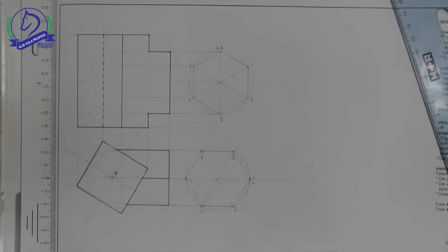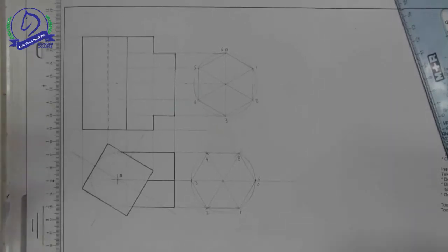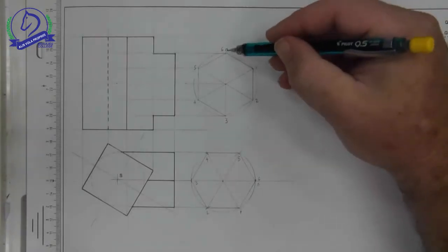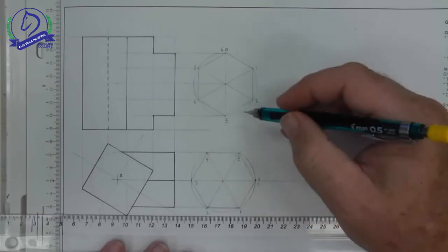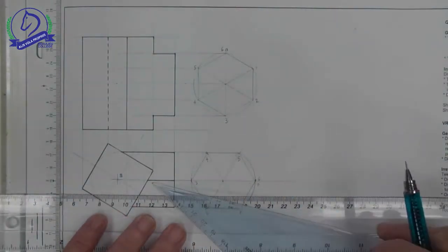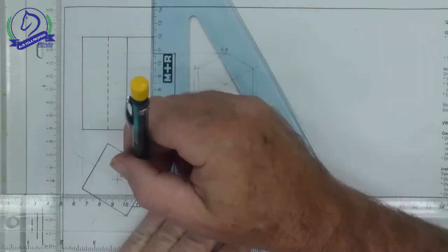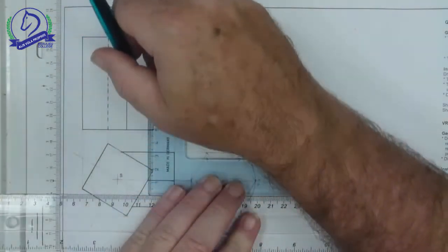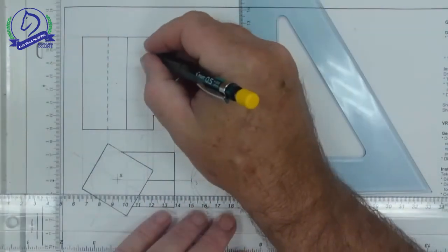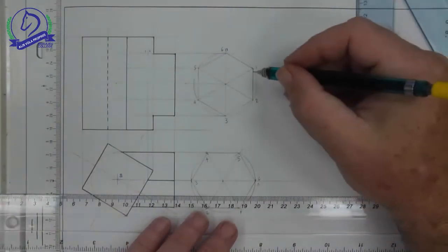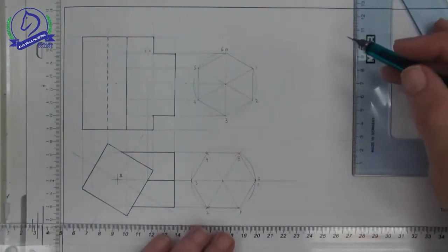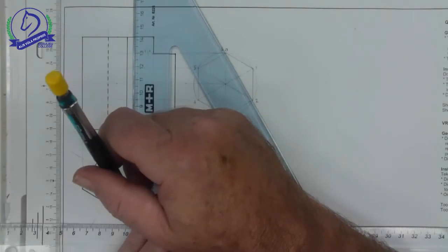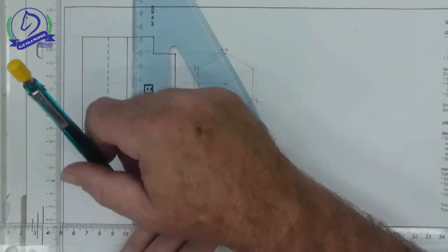Now we can find the curve of interpenetration using the theory of 2 points. I'm going to start with my highest points and work to my lowest points. My highest point is 0 and 6. Where it hits the main pipe, I'm going to project that point up to where it hits point 0 and 6. The next point that I'm going to have is point 1 and 5. Here is point 1. I need to project that up to point 1.